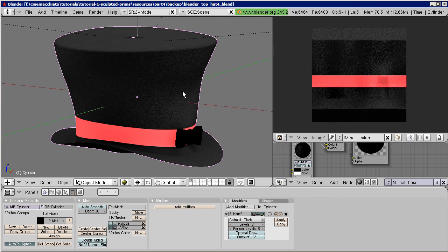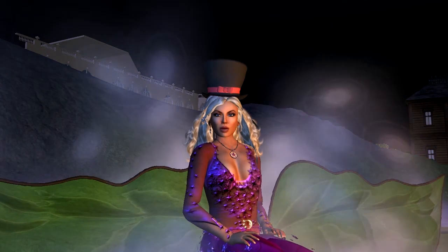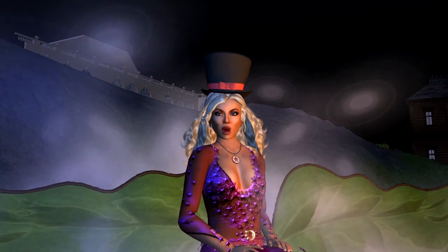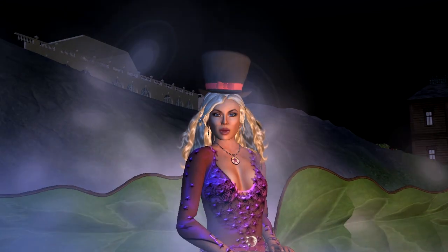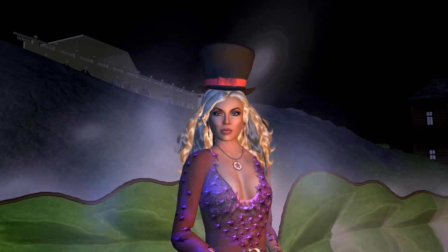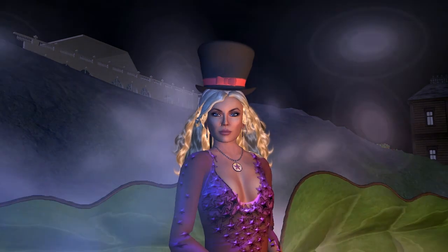So the effect of displacement maps can always also be achieved by directly modeling the mesh itself. Displacement maps are of less concern when dealing with texture baking. But nevertheless, I will show you a nice example where we can use them for our purpose. We already used bump maps when we created the felt surface texture. There we have configured Blender to use a noise texture as a normal map, and by means of this we simulated a high poly surface.